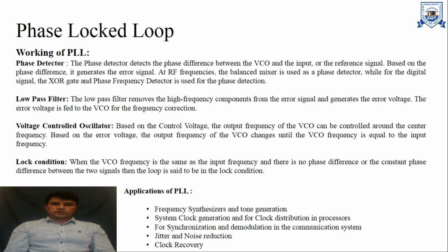Means our VCO works until our reference signal frequency and our output frequency are the same. The phase detector generates error till these f1 and f2 match.